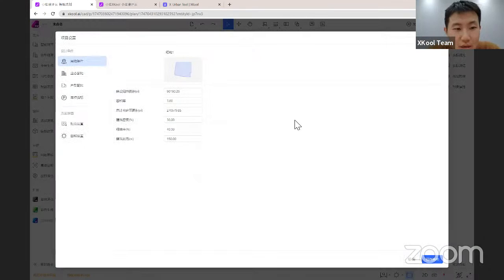So right now we are going to set the several key target indicators or the objectives. Let's say the site area. This is the FAR, or the plot ratio, and this one multiplied by the FAR will get you the allowed constructible area.